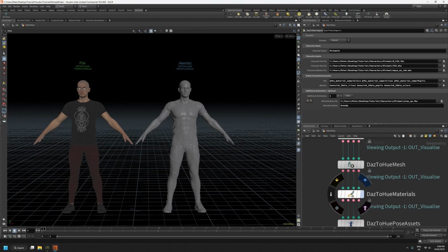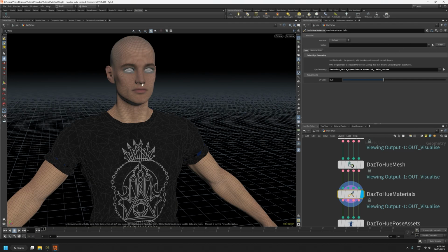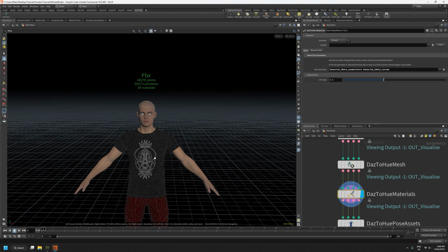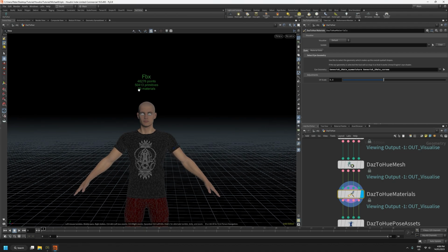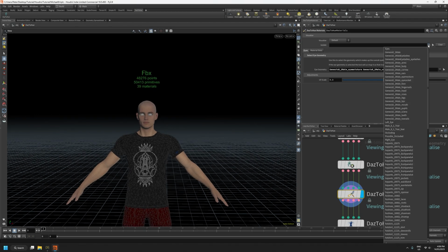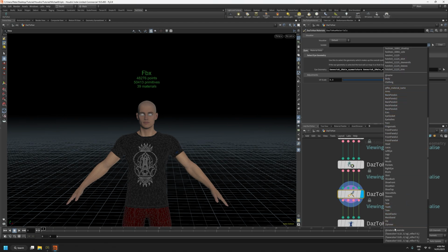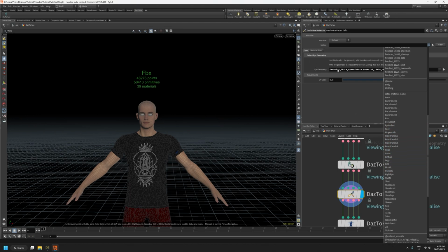So we go back to the materials node. We'll keep working on our character's materials. To unisolate the eyes now. You can see once we've made that change to the eyes, we've gone down to 39 materials from 42. If under the isolate option you have a look at the FBX material name attribute, those are the materials that are still applied to the character. You can see it's created a right and left eye material for us. That was a result of us specifying the eye geometry.